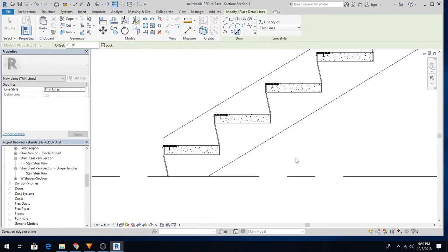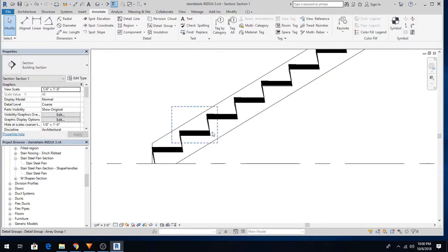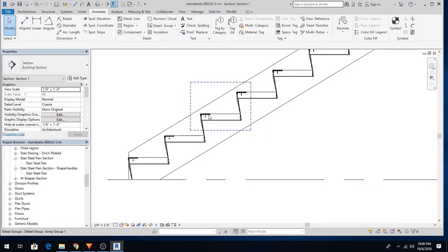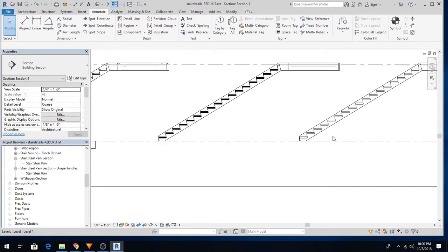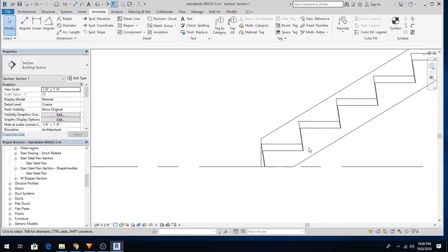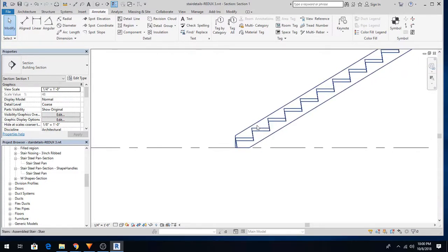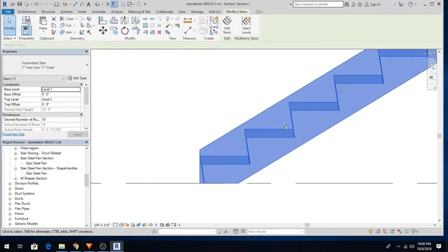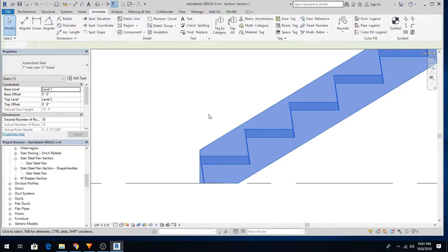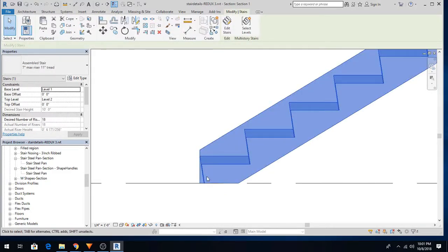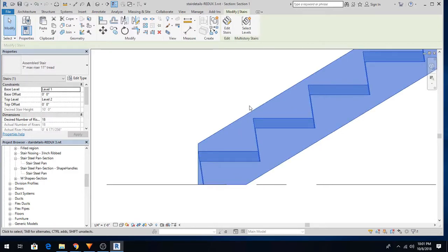If you really want to see these objects in 3 dimensions, if you're going to do a walkthrough or a virtual reality model, where you'd want to see some of this detail, it gets a little more complicated. But as long as you know your profiles and use some of the tools from Revit, like copy and paste aligned, to create the profiles, you should be able to create the details that you need in your stair fairly quickly.